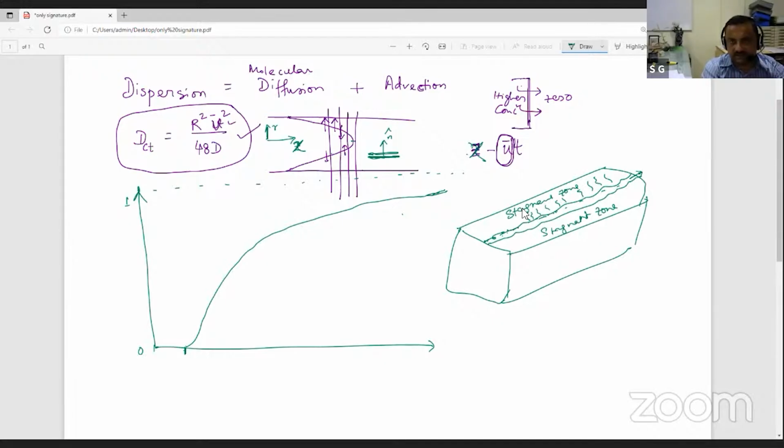This is one way. The second thing is, you can expect a very slow movement of the concentration front through the porous part, probably several orders of magnitude slower than the movement through the crack, because the crack transmits immediately. That movement will also contribute a little bit at the outlet. So you will find that there would be a breakthrough immediately, and the breakthrough would be caused by the flow through the crack.